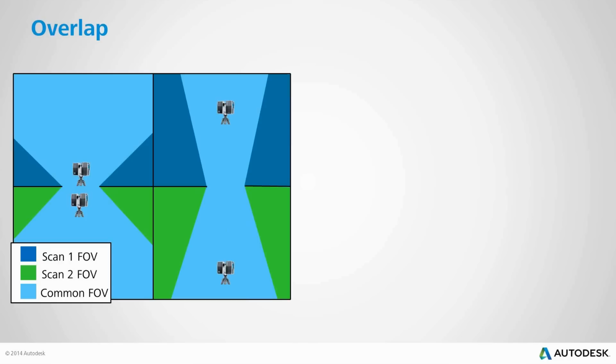In the scenario on the right here, the scans are taken basically from the middle of the room, and the overlap area is small compared to the scans on the left side that are taken much closer to the threshold of the doorway. That overlap can get very narrow depending on how that threshold is. So you want to keep in mind these pinch points, or these narrow thresholds, and how they impact your overlap.